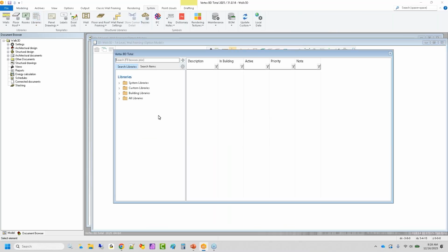Now, with framing, we have those layers that are kind of common. We have the framing layers that you can apply different framing tools to the same layer. So like you saw when I just selected that 4-inch layer of the wall and then applied a framing tool to that layer. With sheathing, it's a little bit different. We actually set up different layers for each different type of sheathing. And we're using kind of a common framing tool on all of those sheathing layers.